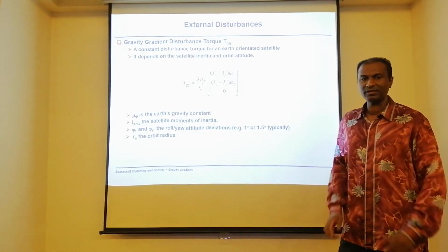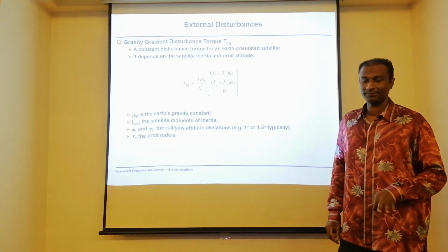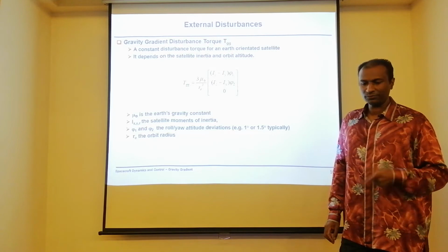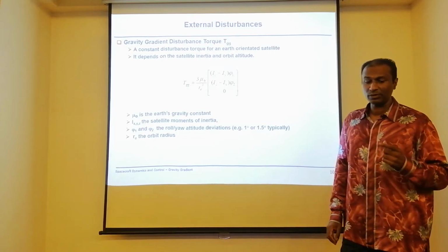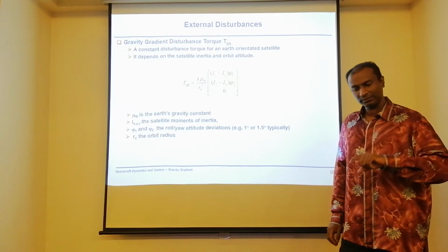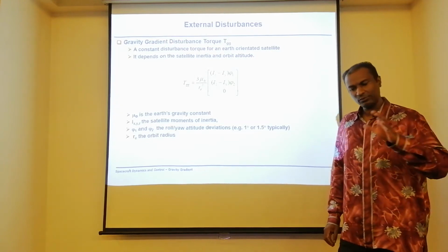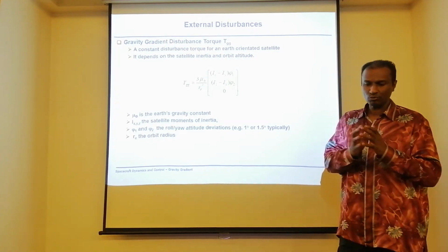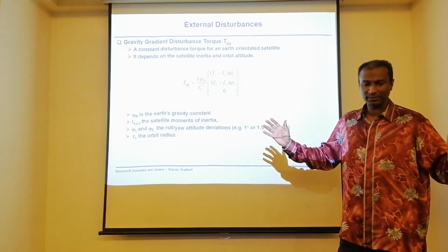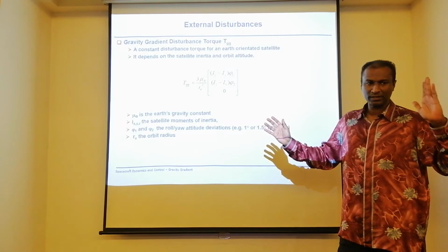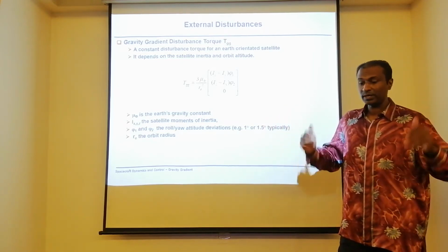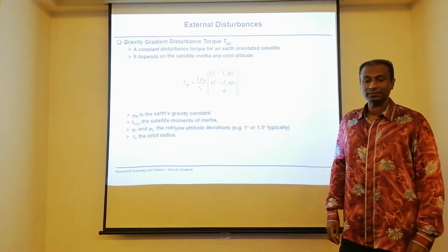All right. Now, talking about all this, we know that we can use the gravity gradient to even stabilize the satellite. But at the end of the day, if we don't calculate the inertia correctly, and don't do the characteristic equation and evaluate inertia x, inertia y, inertia z correctly, then we will be in an unstable region.